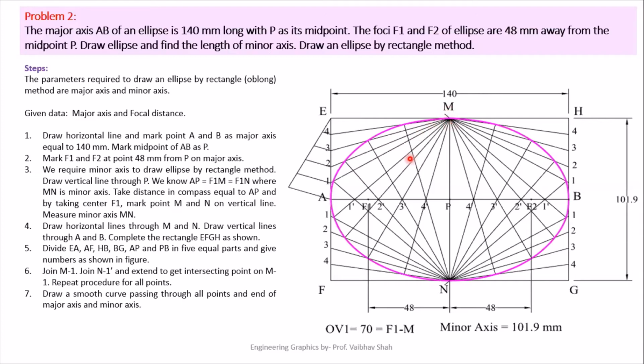Now after that, you will just repeat this procedure on the right hand side. So I will just be repeating the procedure for this rectangle only. You can repeat the procedure for these 2 rectangles by yourselves. So let us divide this portion into 5 number of equal parts. Why 5 parts only? Because we have divided this horizontal number into 5 parts. So we must divide this also into 5 parts.